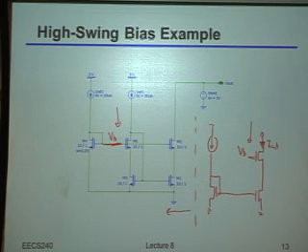I'll maybe give you guys a reminder. What did I say was the absolute number one rule about matching in analog circuits? What was that? VGS. Okay, no, the VGS is important, but I'm saying even more simply than that. When we talked about doing analog layout, and I said, if you want things to match, what do you have to do? Yeah, you have to make everything exactly the same.